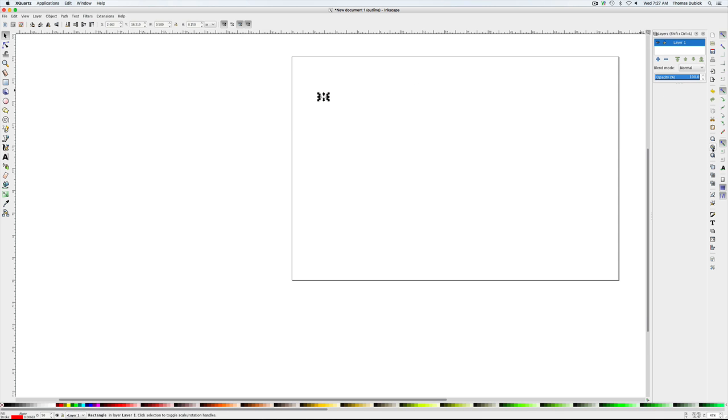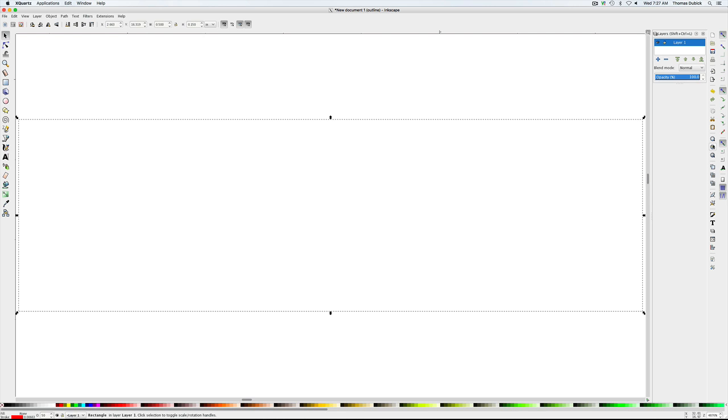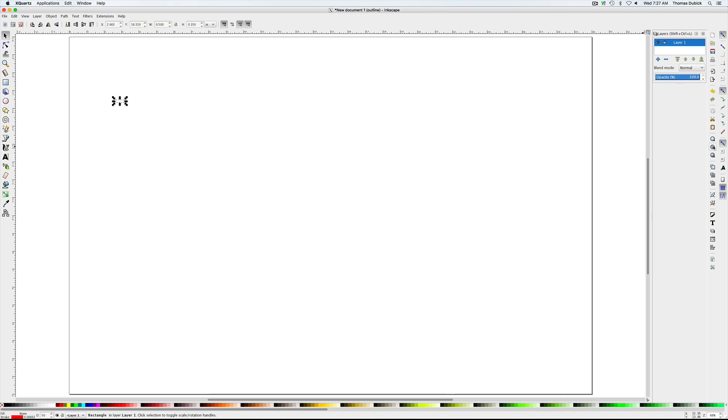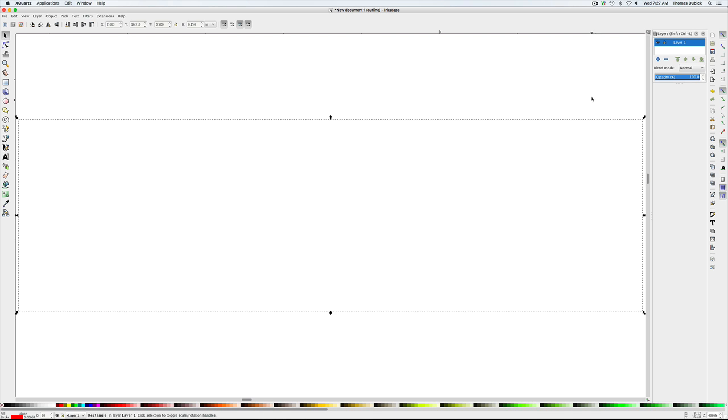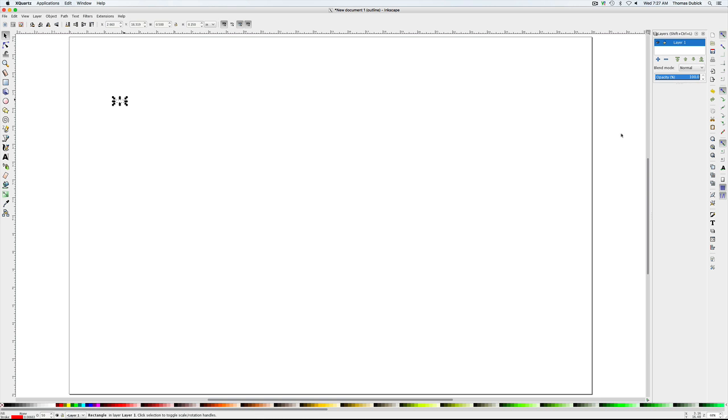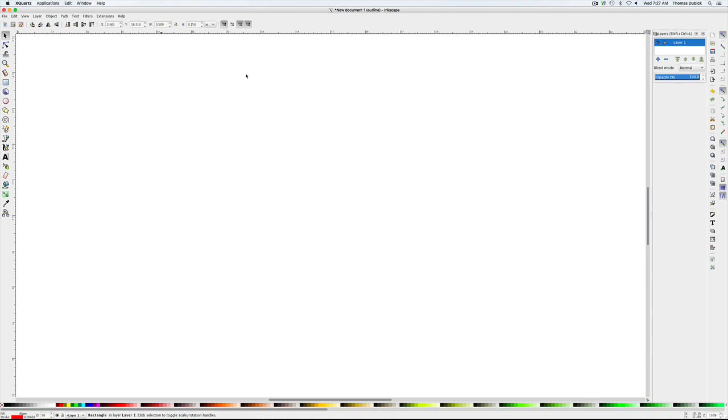Now, when we want to get a little bit closer, we click over. There's 3 icons you can click. That gives you an overall. This will take you right up on what you're doing in that middle icon right there, if you see that. Zoom to fit drawing, zoom to selection, and zoom to fit window. Go back out on that. I'm going to hit positive here and get a little bit closer to it because I want to be able to see it, but I also want to see other things next to it.